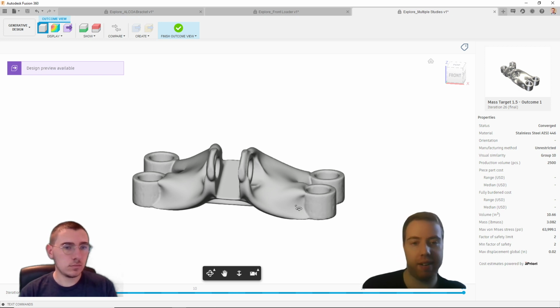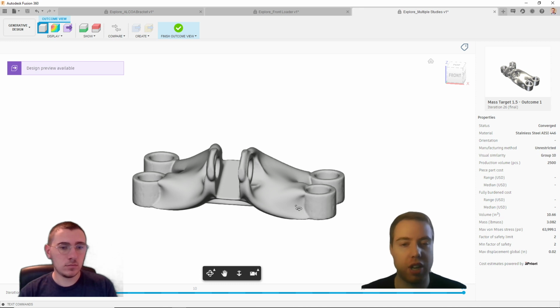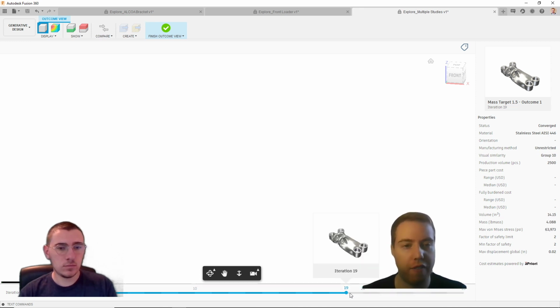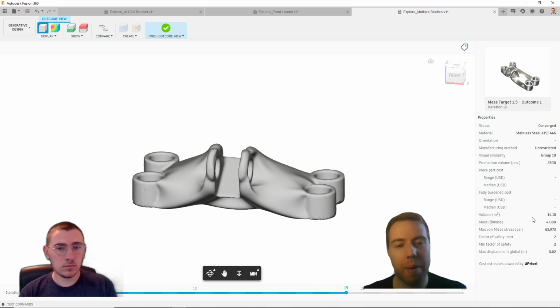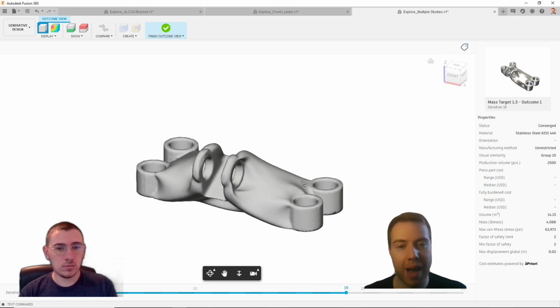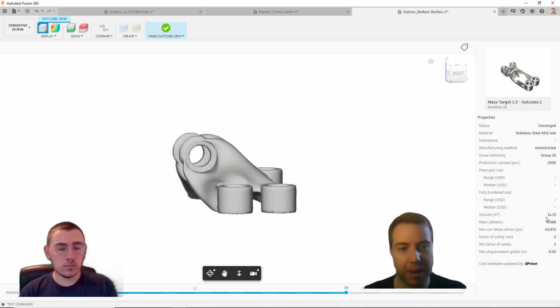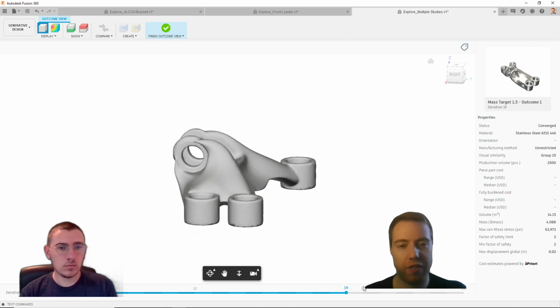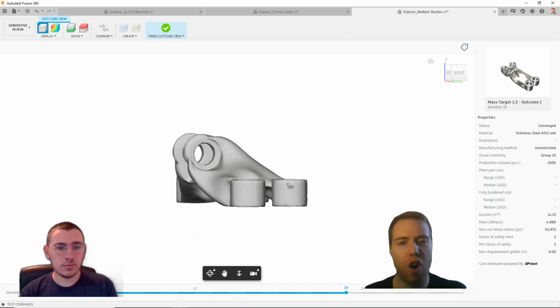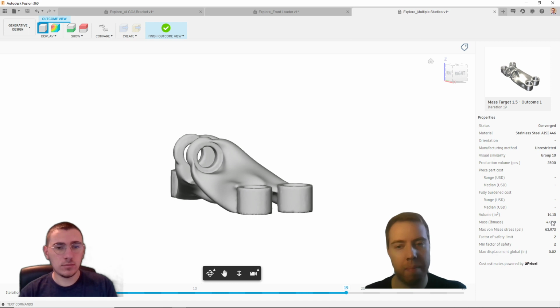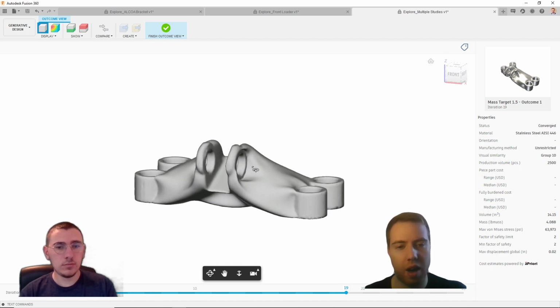For a different material where we're able to bring our design all the way down to that mass target, or if I'd, for example, specified a mass target of 4 pounds mass, then what would happen is when we reach this mass here, we wouldn't continue to take material away or continue to try to reduce the mass. Instead, you'd see your design continue to iterate, but it will hover around this mass, and it will maintain the mass at this objective.